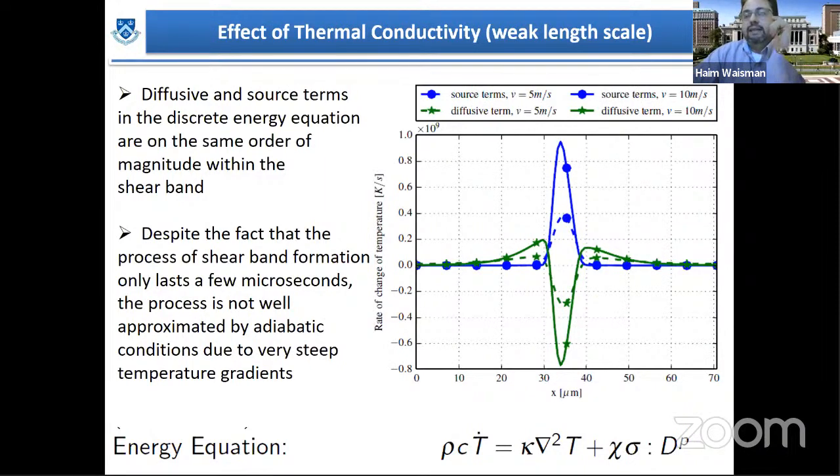So this is the competition that creates a length scale between them. If you add the two together, there will be a length scale created, and this length scale provides a regularization in this case. I call it a weak length scale because you cannot determine what the length scale is; it comes automatically from this model. These are the two terms.